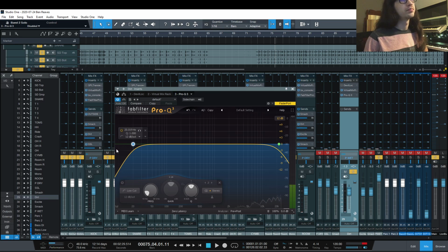On an original source, that doesn't seem to happen. In fact, you usually see your peak level go down when you do that. When it's distorted, the opposite happens because you've already removed some of the peak level by squaring it off, creating those artifacts. And then you create a brand new artifact by introducing this strong phase shift.